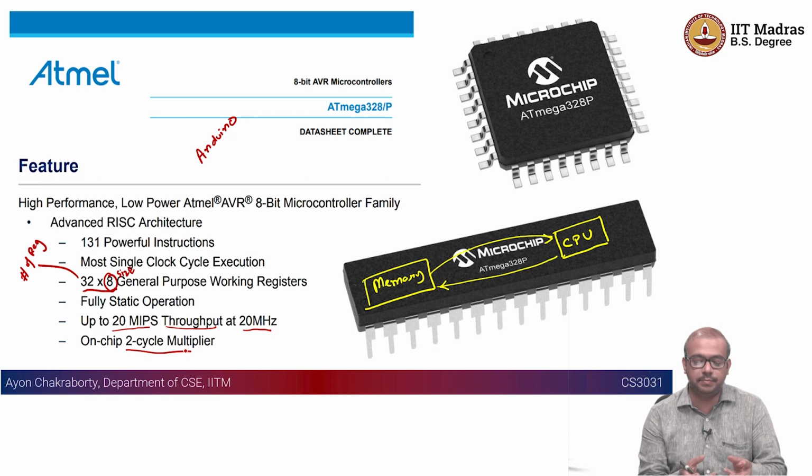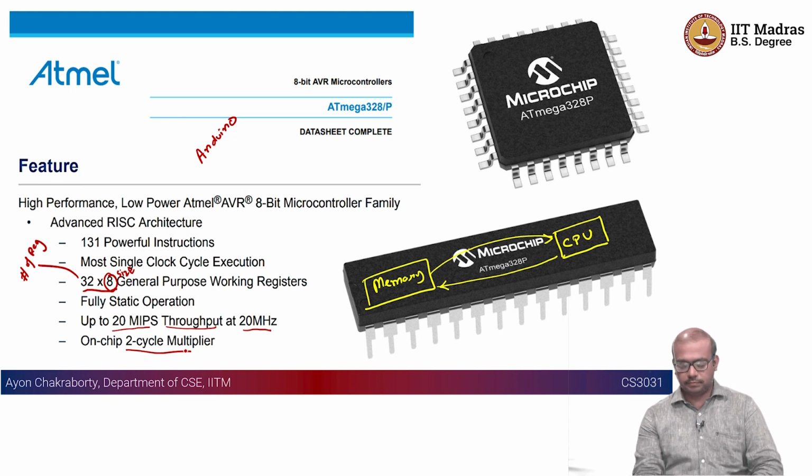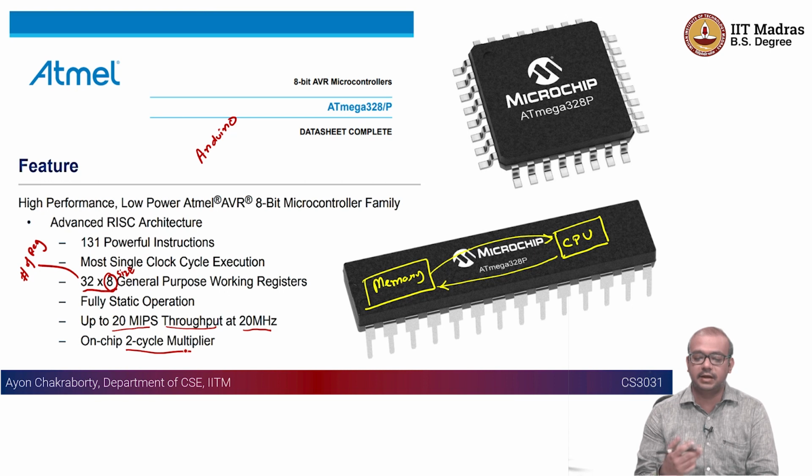I found this CPU with an interesting feature they want to talk about, which is multiplication, and my application might require multiplication a lot compared to other kinds of instructions. So this is something that you should then buy, right? In this particular instruction set architecture, they have specified a multiplication instruction, and they clearly say that it is going to require 2 cycles.